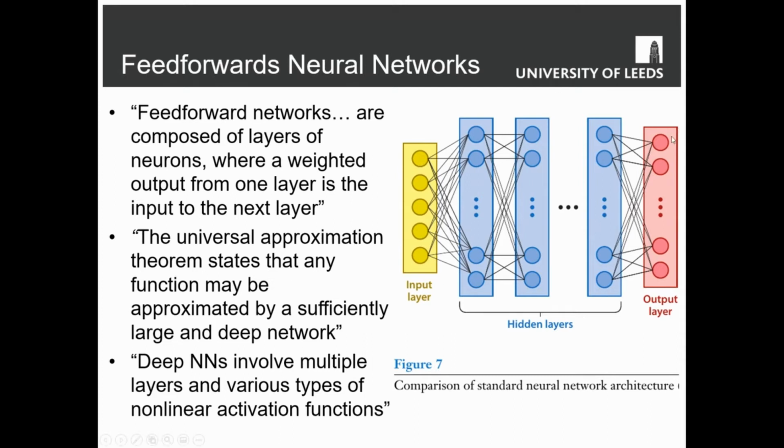And then the output layer is a vector which will contain a set of values which define the output flow field. So in our flow problem analogy, maybe there's a grid, let's say, with 100,000 finite volumes in, and for each of those volumes, our output is going to be u, v, and p at the center of that volume. So this might be an output vector with 300,000 values in, and this input vector, as we've shown here, is 5. On the other hand, our output vector might be something completely different. If we're only, for example, trying to predict the drag and the lift around an object in the interior of the flow, our output layer might just have 2 values, the drag coefficient and the lift coefficient. So the output layer will vary depending on what it is that we're trying to get our learning model to predict.